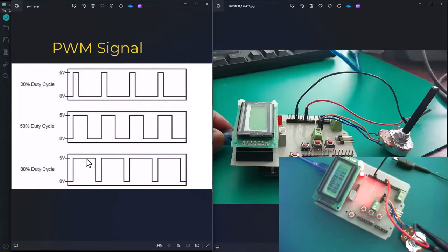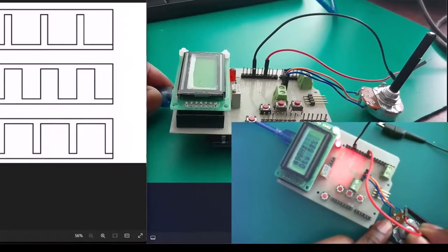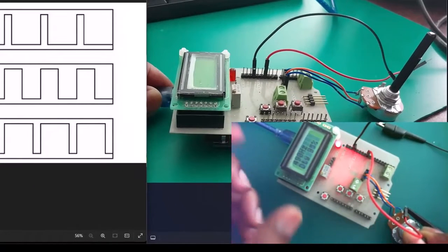Now, this is one signal that might be changing pulse at different times, right? Because you can control it. That's where the modulation comes in. You're not going to have a PWM without a controlling component, because PWM is basically a technique used to encode a message into a pulsing signal, a signal that is changing on and off. Now, here, if we go from 80% duty cycle to, let's say, 100%, as you can see here, I'm changing the duty cycle of this signal.